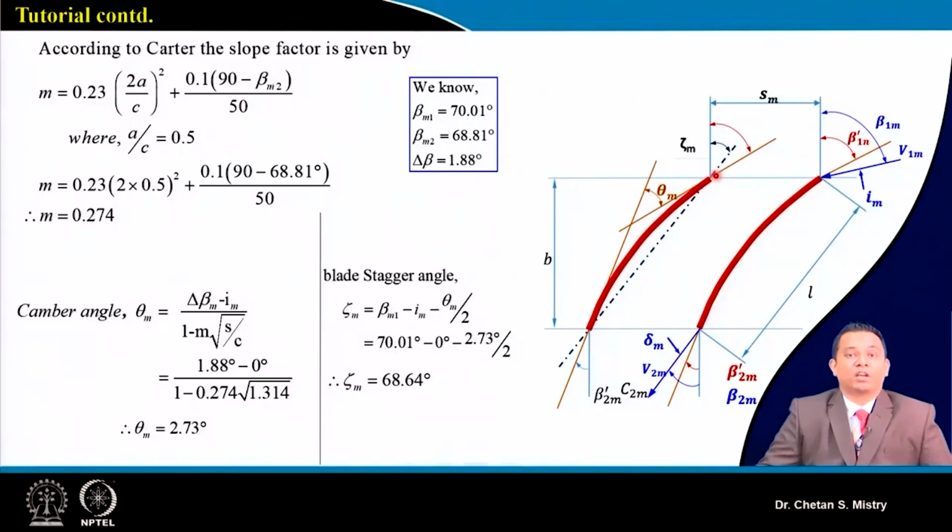As we have discussed earlier, if you bend the plate and it is rotating, that also will generate a pressure rise. There is a special requirement of aerofoil when we expect our pressure rise in a systematic way, because we have a pressure surface and a suction surface. We have flow acceleration and deceleration on the pressure surface as well as on the suction surface, and that decides my pressurizing capacity. Here our expected pressure rise is low, and that's the reason we will be bending this plate.